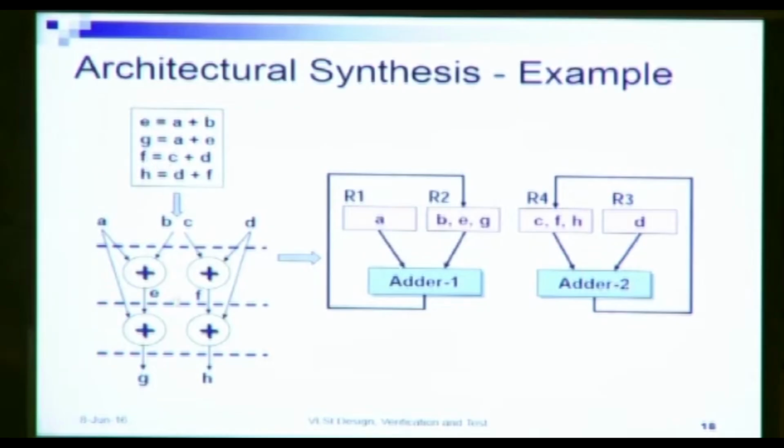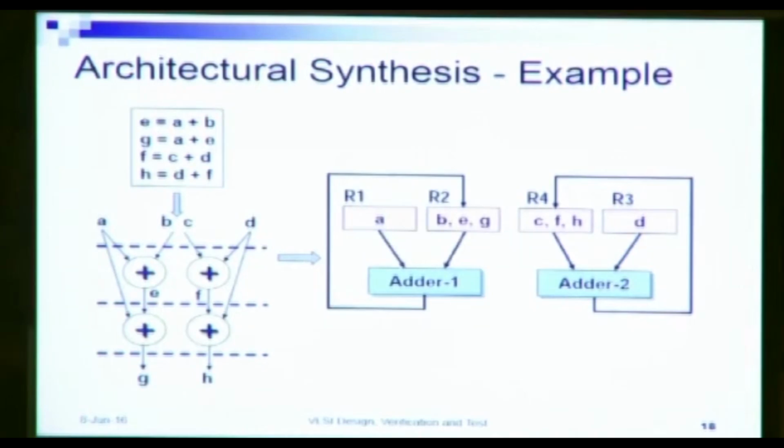So first, what do we do? We identify the hardware components, resources that we require, and we understand here that we require adders and registers to implement this particular behavioral description. Now this behavioral description then will be scheduled. So this process is scheduling. This shows 2 time steps.